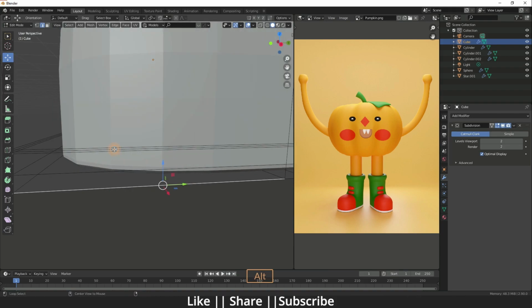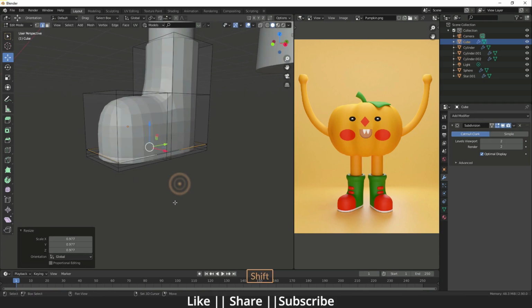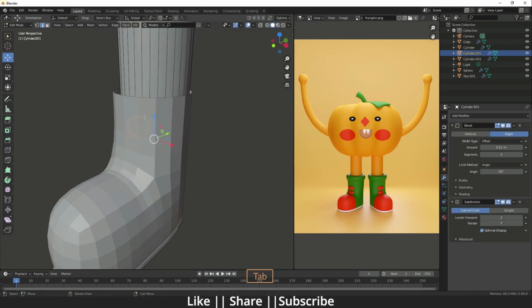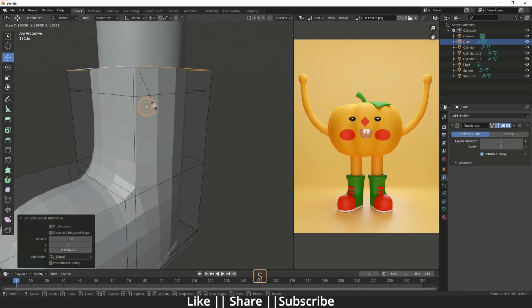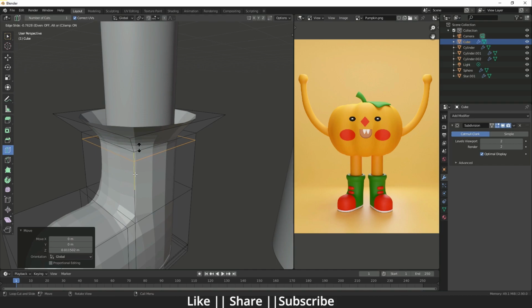and then I'm just going to select this edge, and then I will scale inside. It should be a little bit inside, not too much. Yeah, I think that's fine to me. Okay, and then we'll select this part, and we'll press E for the extrude, and then I'm just going to scale it something like this. And after that I'm just going to add one supporting edge loop here.